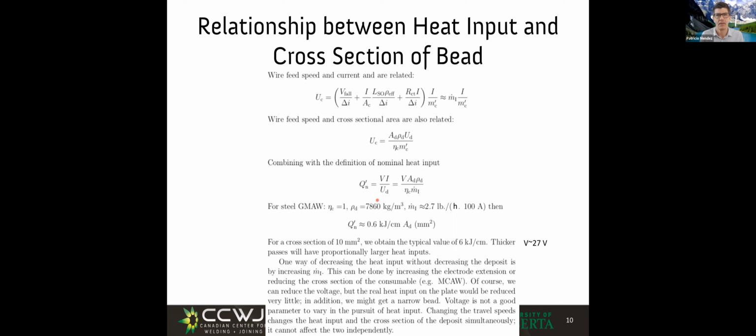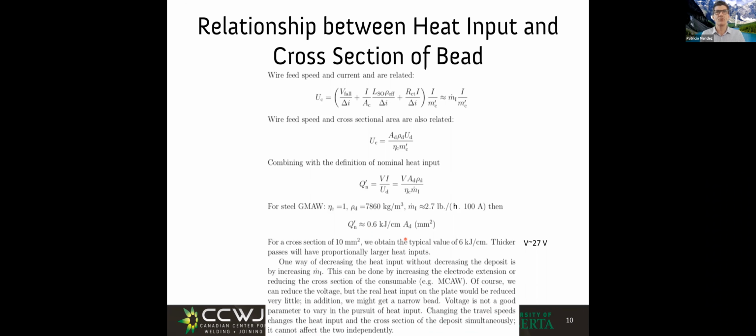On Tuesday, we'll start discussing, if you have the heat input, can you calculate the cooling rate, T8/5? Can you speculate about the size of the heat affected zone? And all those things start to come out. Very, very interesting. So this is a practical number. Any questions about deposition and mass balance in welding?